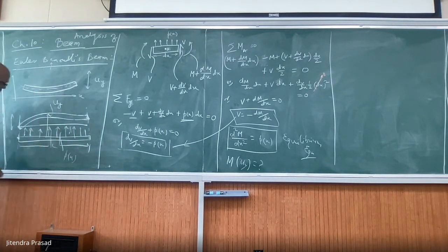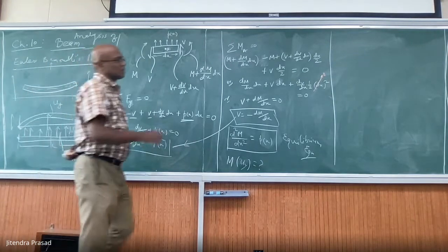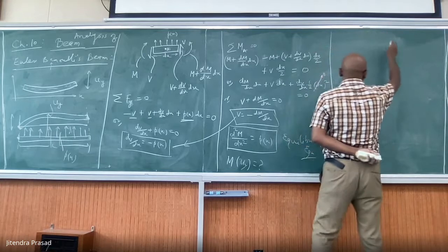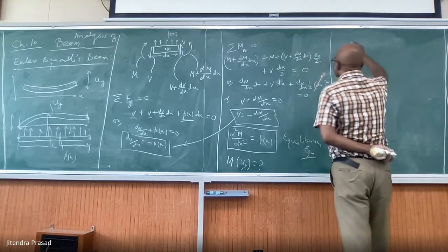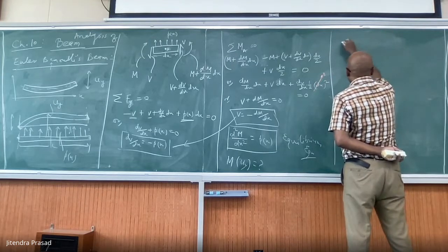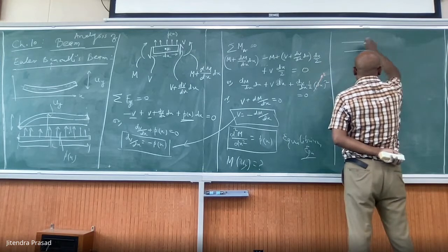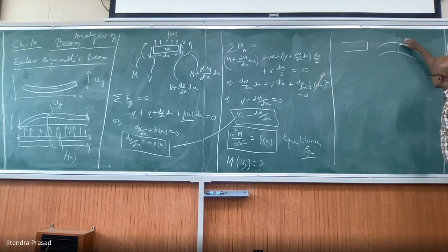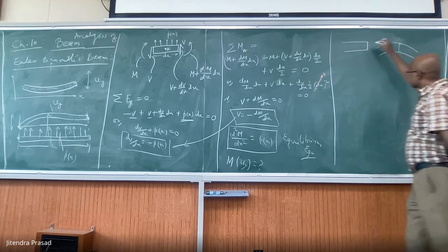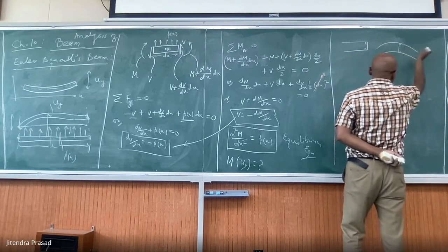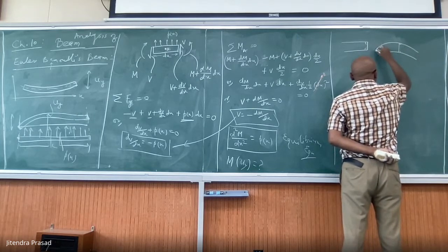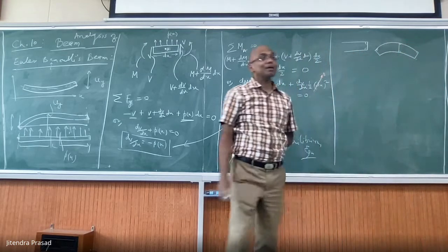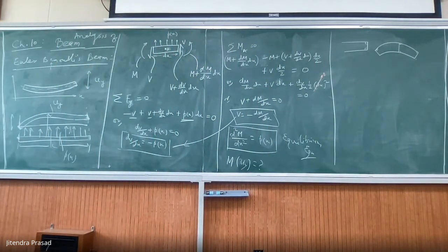When we say Euler-Bernoulli beam equation, it has one assumption that actually is not correct, but still it simplifies the problem. And what is the assumption? If the beam is like this, let us say, imagine after it's loaded, and if it deflects like this, then it says that this angle remains the same. This is 90 degrees. So at the end, it has to maintain 90 degrees. All the sections, the cross sections, will be perpendicular to the surface.